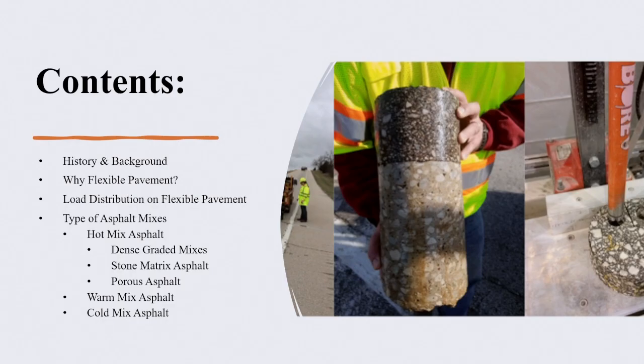After this, we will delve into different types of asphalt mixes. In the US the lion's share of the asphalt is still HMA, or hot mix asphalt. I guess it's going to be the same thing in Nigeria, right? Some states and some references call it ACHM, asphalt concrete hot mix, or HMA, hot mix asphalt. Under hot mix asphalt, we do have dense graded. This is the standard mix.